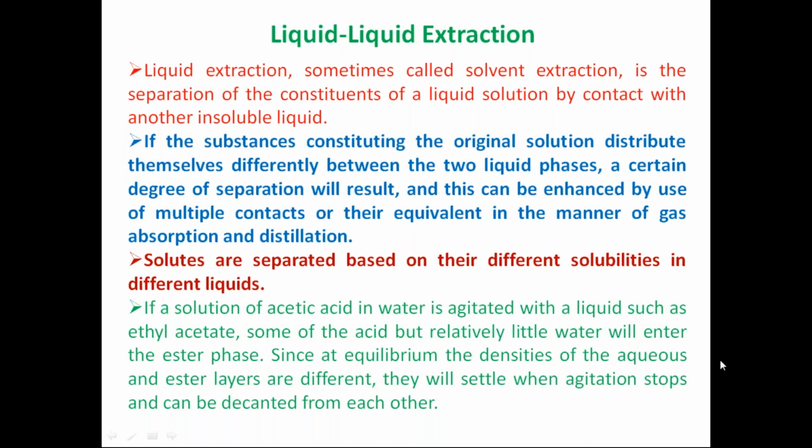Maybe certain partial miscibility might be there, but the component which we are calling C, the solute, will be miscible in both the phases, and it makes equilibrium at certain concentrations between these two phases. Therefore, liquid extraction is also an equilibrium operation.